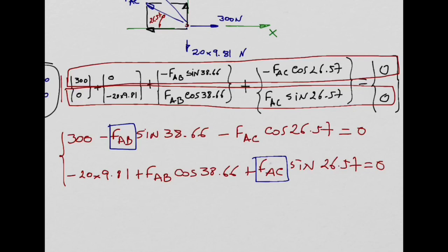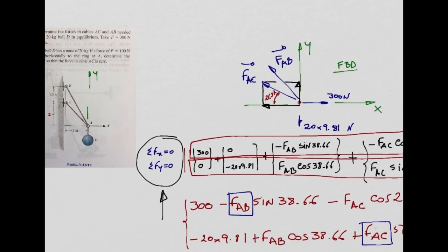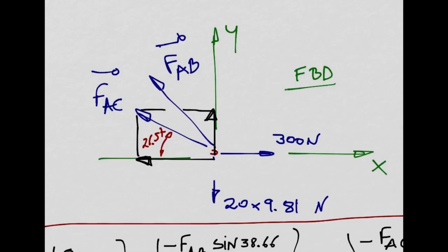You see, if you do this kind of problem following this methodology, creating the free body diagram is extremely important. This is the most critical thing, in my opinion, the correct construction of the free body diagram. You have the body you are analyzing. In this case, it is a particle. Particle A is our body. We isolated that body. By isolating, I mean we need to represent all the forces that were acting on that body, right?